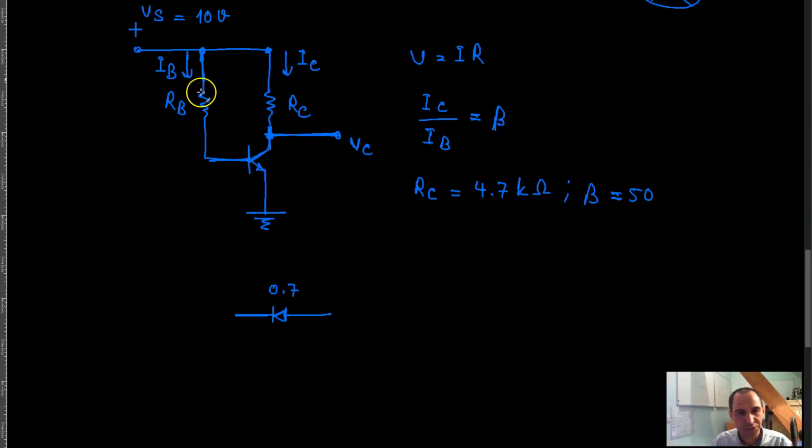But if your supply voltage is, for example, something like 5 volts, then you need to take these voltage drops into consideration, because this is something like 1/5 of the voltage, and in such cases this is important.